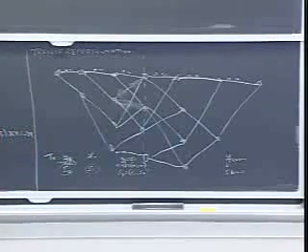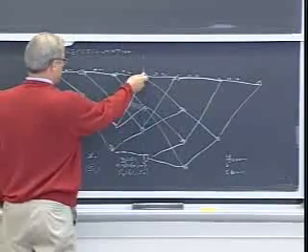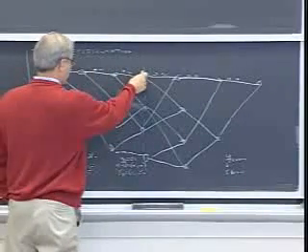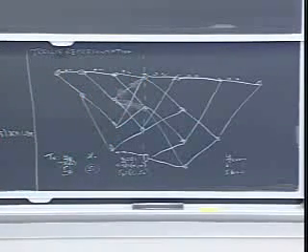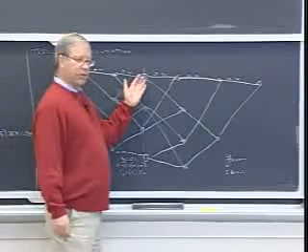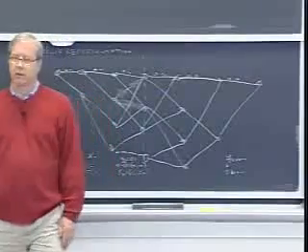All right. Claim: I can pick the minimum cost path to this node, throw away the other possibility, and I can never have thrown away something which itself is part of the minimum cost path through the whole trellis.